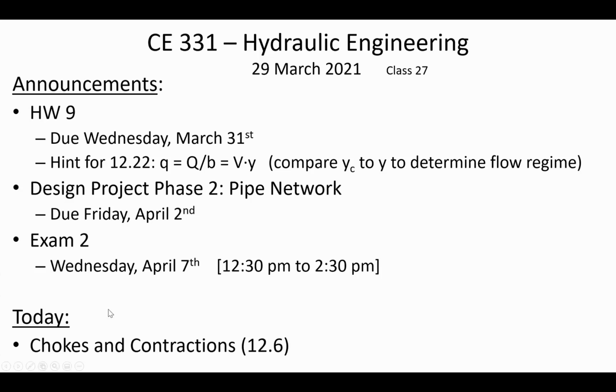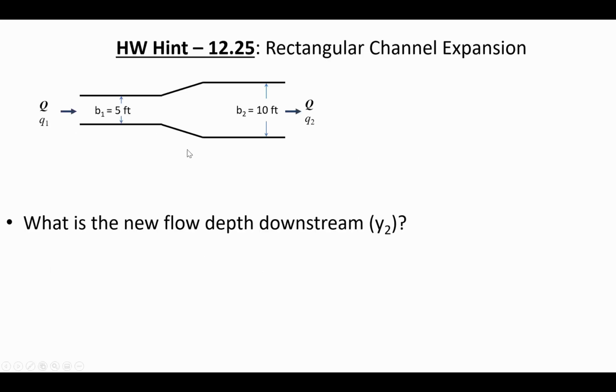Okay, we'll talk about chokes and contractions today, and this is just an application of specific energy. But I mentioned I had one more hint on the homework that I wanted to give you. In homework problem 12-25, I think it's the second one of the three that I assigned, is a channel that's expanding from 5 foot in width to 10 foot in width. And they're asking what's going to be the new depth of flow downstream.